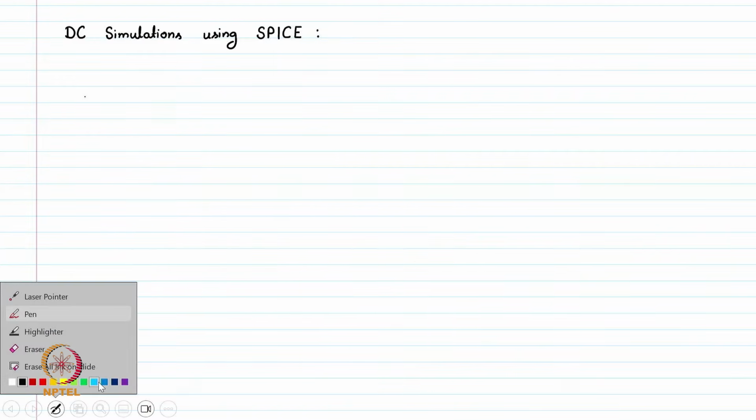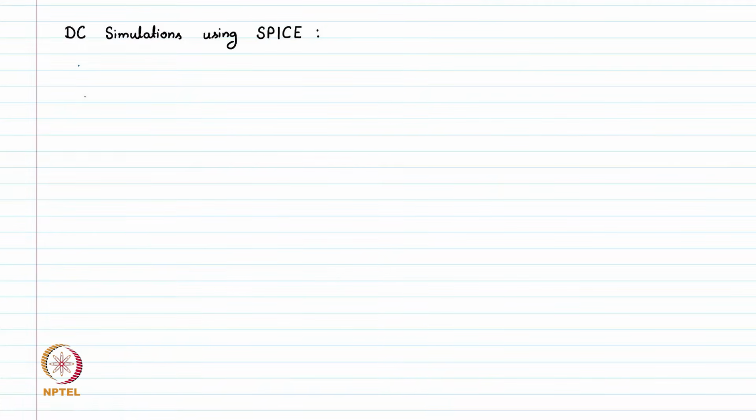So, we will discuss the DC sweep, or we sometimes call it the .dc statement. This is the SPICE directive or command which we use to do the DC sweep.